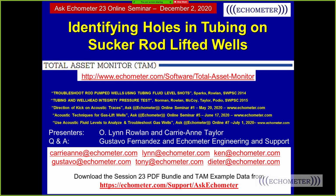The dual shot method is a good technique to find the depth where pressure communicates between the tubing and casing annulus. That means there's a hole, a check valve, or a bad gas lift valve, and all three of those behave the same. If you have a gas gun on one side of the tubing and another on the other side, and one side makes noise and the other side doesn't, the side that didn't fire is just listening.